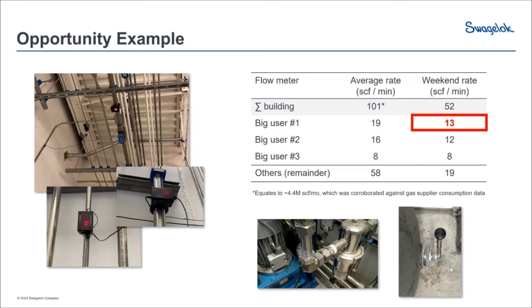And now that the customer was more informed, they can make better decisions, right? Better decisions around how to add capacity, as well as maybe identifying opportunity for them to challenge some of their current purging protocols. And what's really nice about this survey for the customers is they were able to quickly tighten up what was found, and they got a heck of a value out of it. They cleaned up over $15,000 a year in annual nitrogen leaks, and it was a really quick payback on that service.